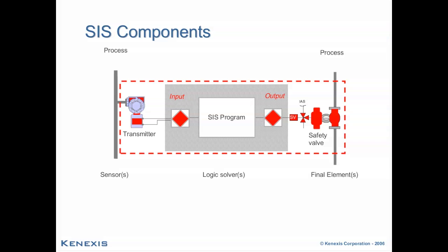During the development of the ISA standard, importantly, it was recognized that not only that logic solver, but also the sensors and the final control elements could play a critical role in ensuring the overall functional safety of a plant. At that point in time, the standard was somewhat broadened to include elements such as safety transmitters and safety final control elements, including shutoff valves or motor starter equipment that could play an important role in achieving functional safety.